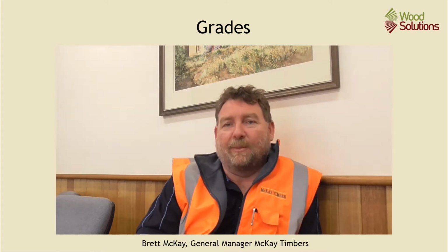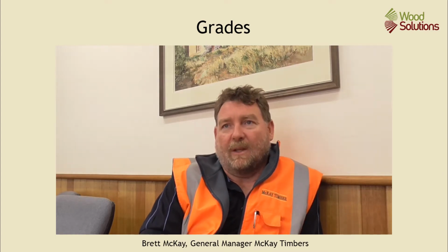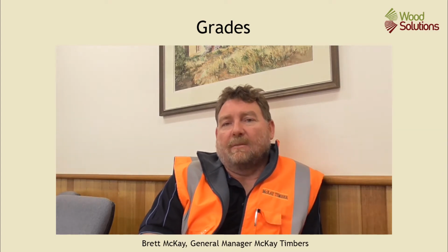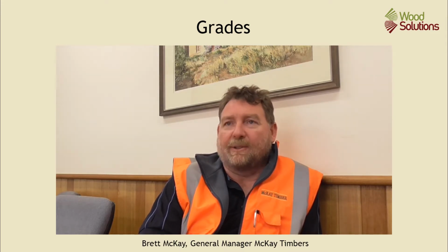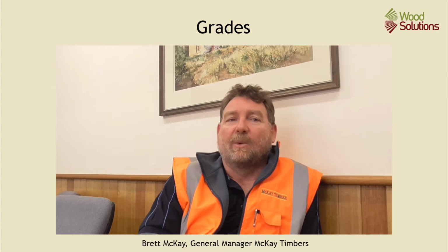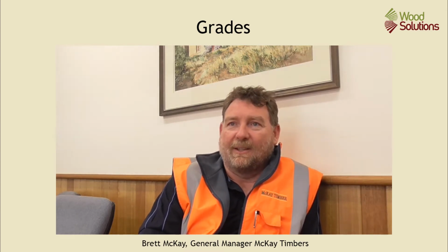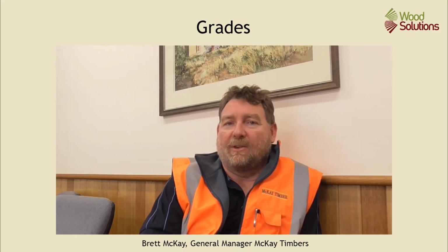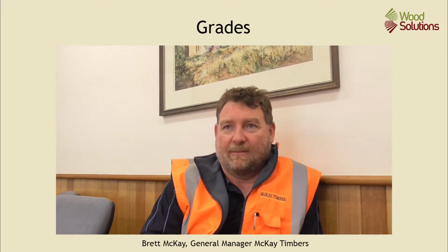We grade both structural and appearance grade in green and dry, mostly in your dry, because even though the product is still got the same strength characteristics, it's got the appearance of a clear board that can go into flooring, to joinery, to cabinet making, whereas a framing grade can have face checking, can have some knots, more gum, just more characteristics, and drying degrade is allowed in a structural product than in an appearance product.